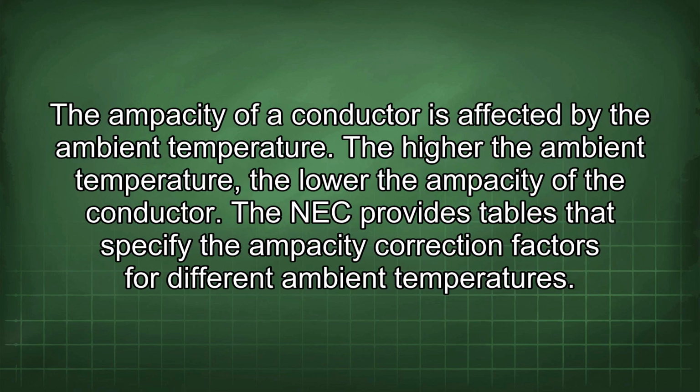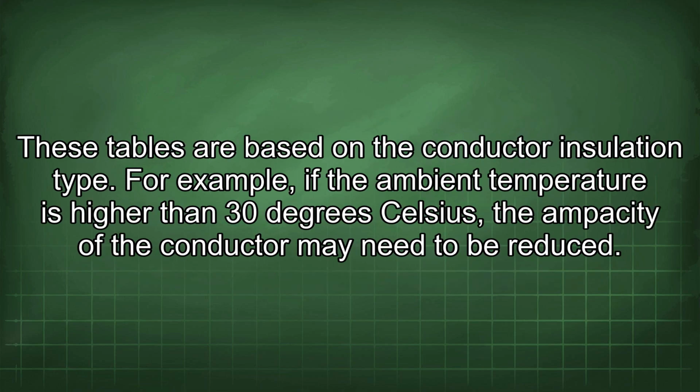The ampacity of a conductor is affected by the ambient temperature. The higher the ambient temperature, the lower the ampacity of the conductor. The NEC provides tables that specify the ampacity correction factors for different ambient temperatures. These tables are based on the conductor insulation type.